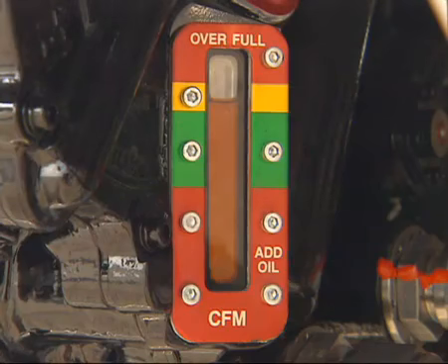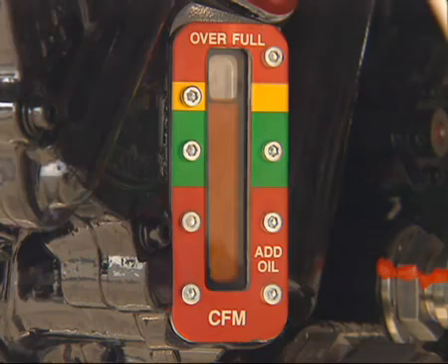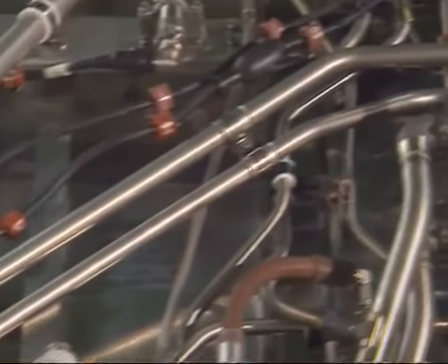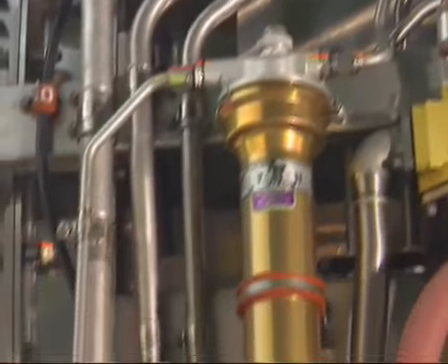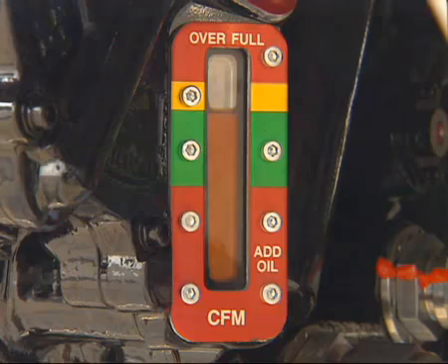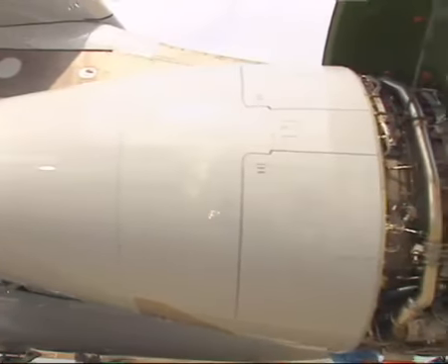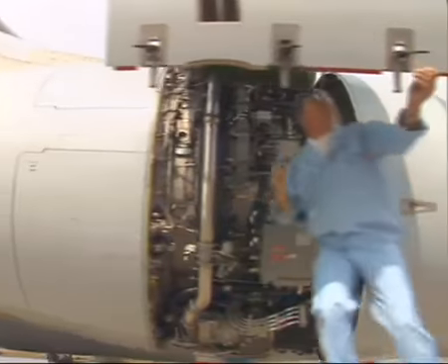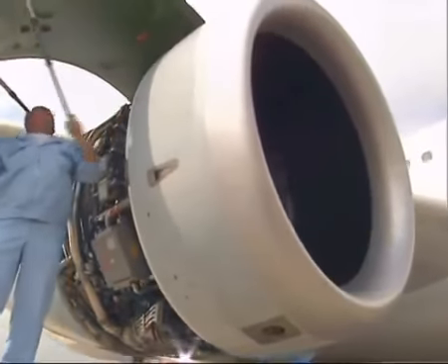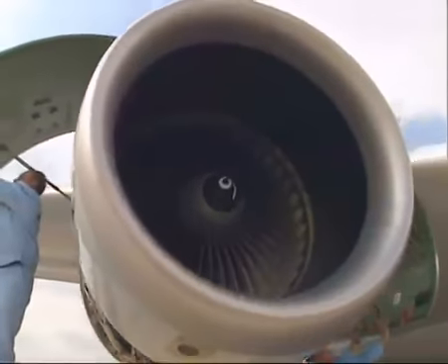The oil may be slightly above the top of the green band due to thermal oil expansion. However, the oil level may have dropped due to the presence of air in the system before the motoring. Look at the oil level sight glass again to ensure that the oil level is optimum. Good servicing is a key factor in ensuring a smooth and long IDG operating life. It contributes to the operational reliability of the aircraft.